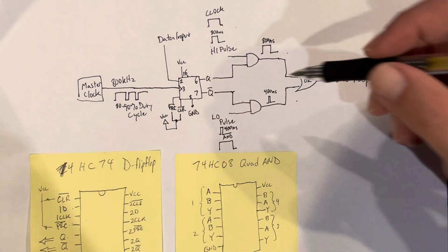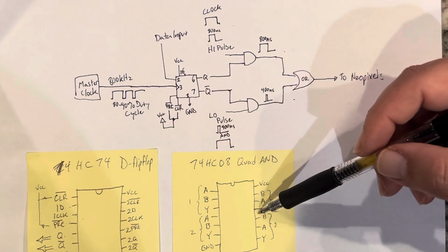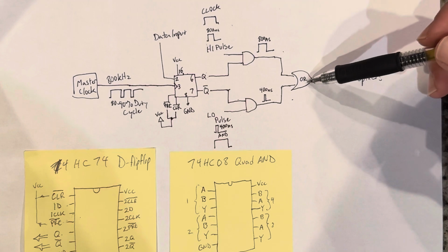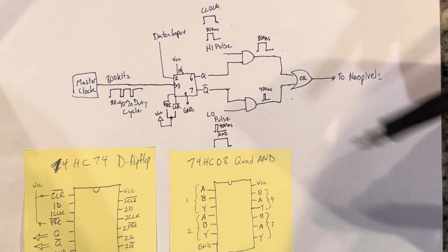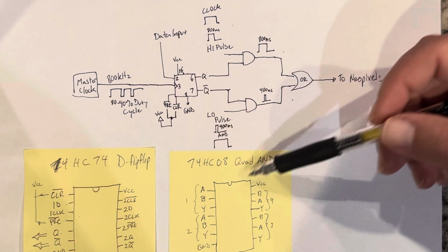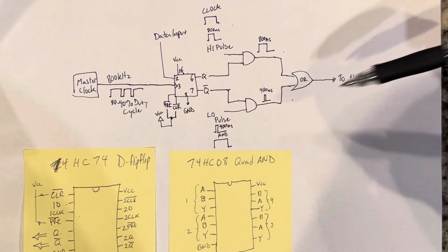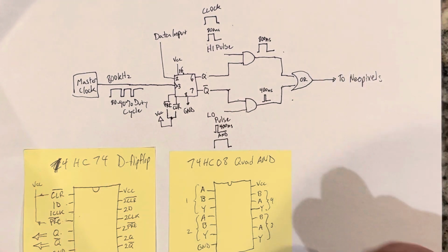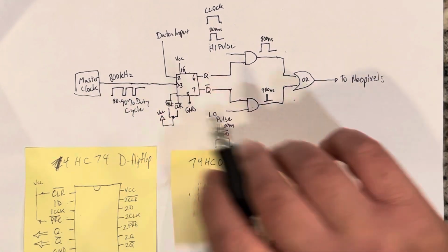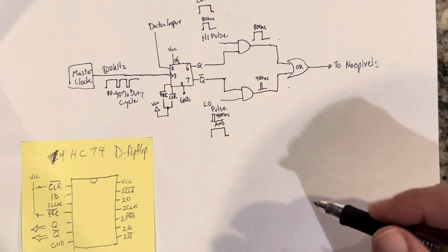All right. So these could be done with the AND gate, such as this, and these could be done with a separate OR gate. At the time when I was building the circuit, I did not have these chips, and I did not have these chips, which I still don't have, actually. So the way I did the AND gate is different. I made the AND gate using transistors.